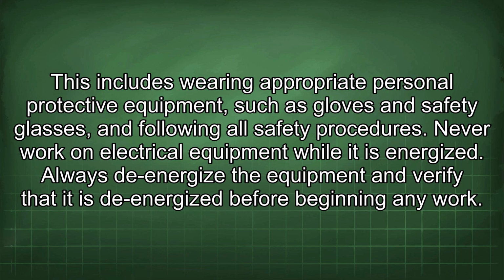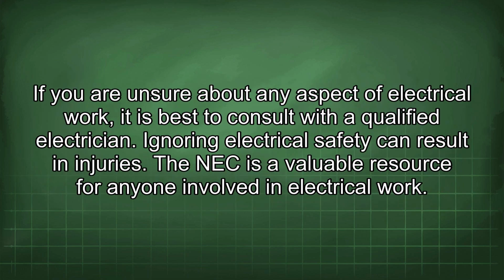Never work on electrical equipment while it is energized. Always de-energize the equipment and verify that it is de-energized before beginning any work. If you are unsure about any aspect of electrical work, it is best to consult with a qualified electrician. Ignoring electrical safety can result in injuries.